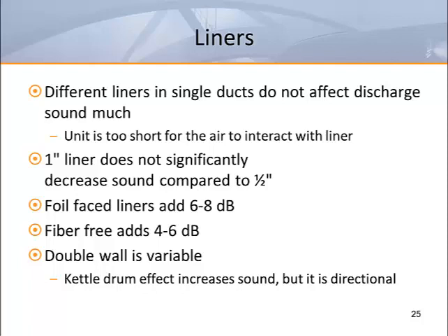This tends to create higher discharge sound levels, but it can also add transmission loss to the casing, resulting in lower radiated sound levels. In fan-powered units, dual-wall construction can make radiated sound levels harder to accurately predict. The high transmission loss can create a directional sound that exits through the induction port. In large open plenums, this would likely not be an issue, but in confined ceiling spaces it can cause problems. In the case of fan-powered terminals with dual-wall construction, AHRI 885 will generally predict higher sound levels than those that will be actually heard due to the directionality of the sound.